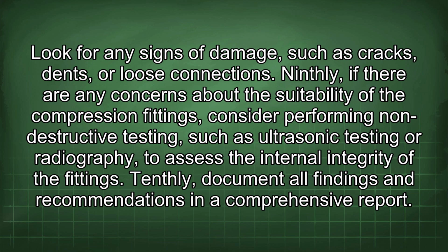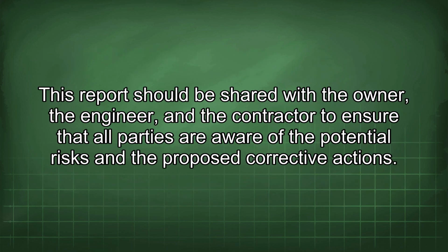Ninthly, if there are any concerns about the suitability of the compression fittings, consider performing non-destructive testing, such as ultrasonic testing or radiography, to assess the internal integrity of the fittings. Tenthly, document all findings and recommendations in a comprehensive report. This report should be shared with the owner, the engineer, and the contractor to ensure that all parties are aware of the potential risks and the proposed corrective actions.